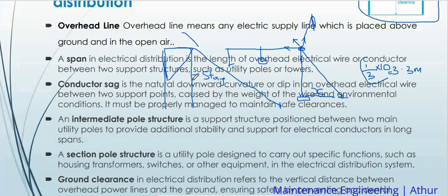It is not only when people refuse, but when you find that the pole is near the road, and when you calculate the distance that is supposed to be standard for the stay, you find that it is supposed to be pinned in the road. There we use what we call an outrigger stay.